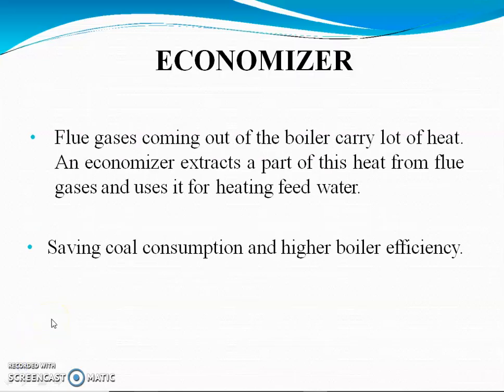Another important component is an economizer. Flue gases coming out of the boiler carry a lot of heat. An economizer extracts a part of this heat from flue gases and uses it for heating feed water, saving coal consumption and giving higher boiler efficiency.